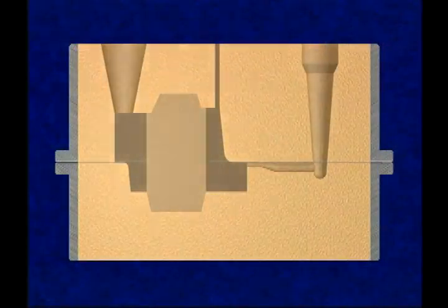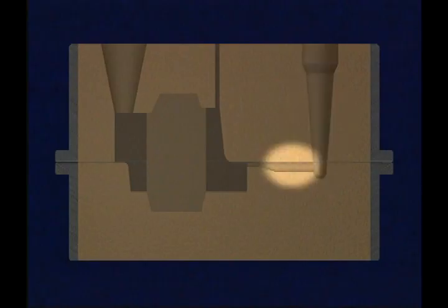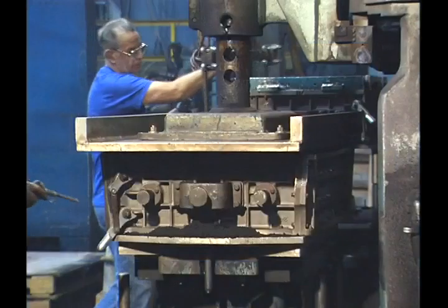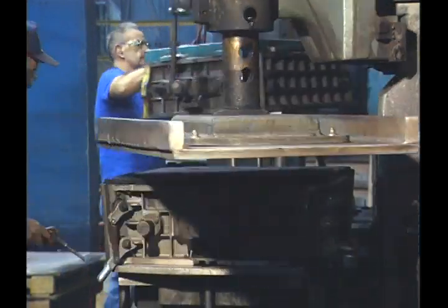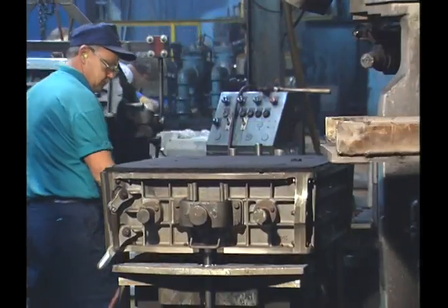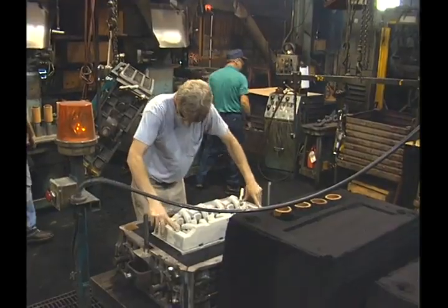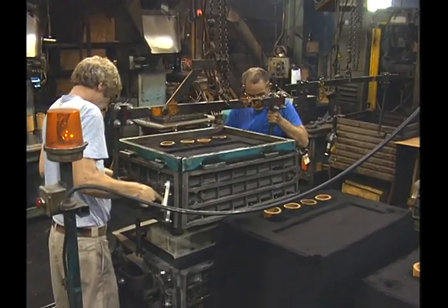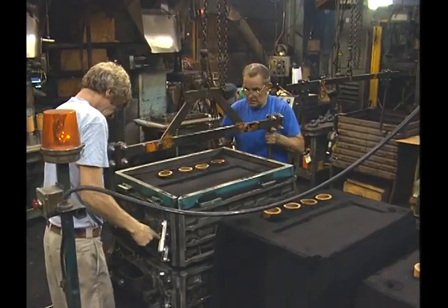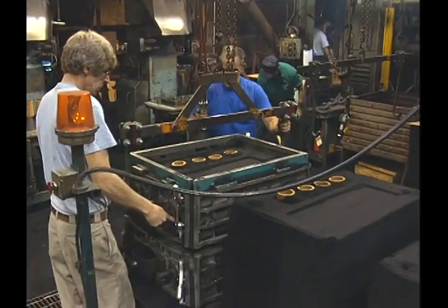This system includes a pouring basin, sprue, runner system, and one or more gates. Once the sand has been compacted, the pattern and mold half are separated, and any loose sand is blown away. Cores, if required, are inserted into the mold. Once they are set, the mold is closed by aligning the cope and drag. The mold is then transferred to the pouring station.